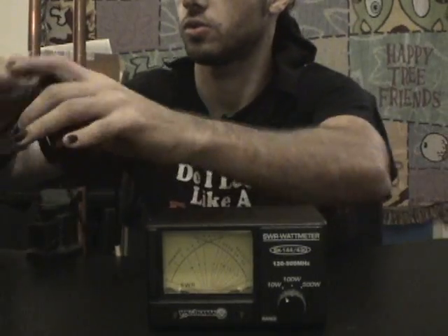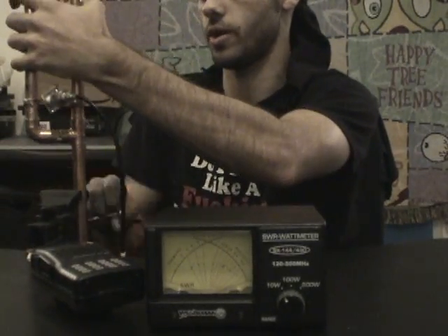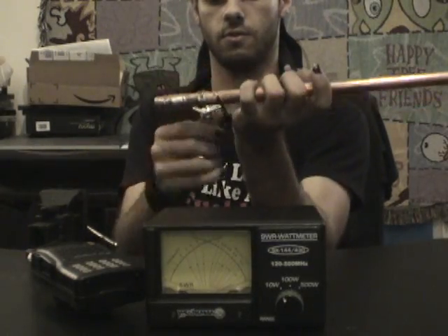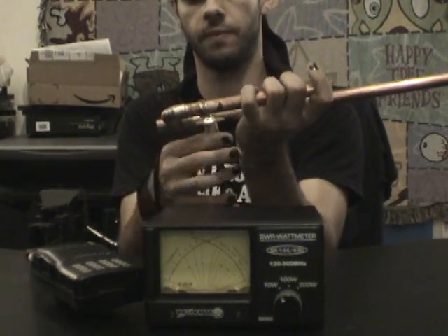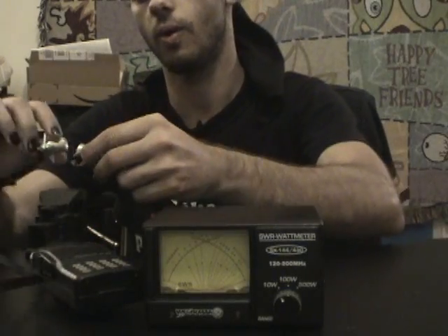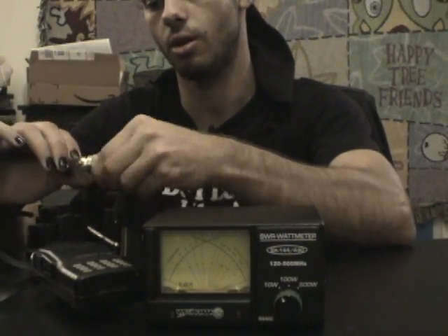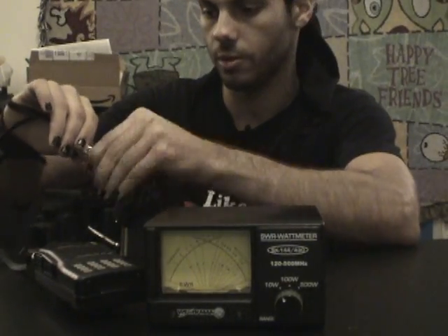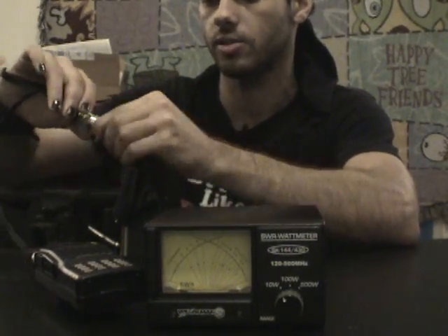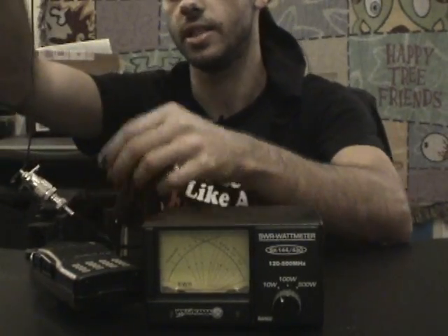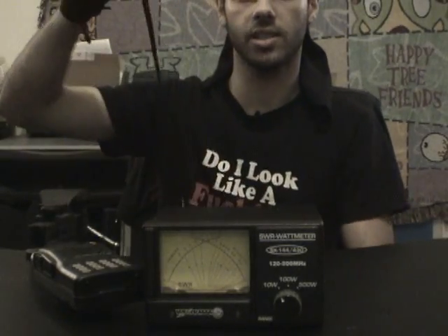Let's go out and switch to this ladder line antenna real quick. So we're just going to take this, that pulls off. Now, I am actually going through a lot of gender benders, and a lot of different coaxial types, which is throwing the SWR off. So whenever you're actually building this, make sure that you're taking your coaxial cable into account when dealing with the SWR.